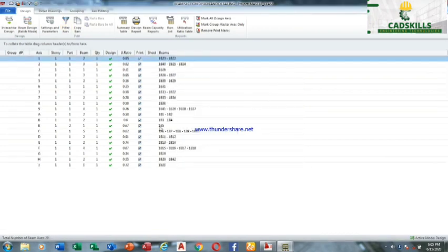Okay, now in this case, I will filter those second floor beams off, because I can use one beam here to edit as my roof beam. All right, so it's not a big deal. Now I only want story 1 beam to appear. I don't want any story 2 beam to appear in my report. So that's what I've done now.